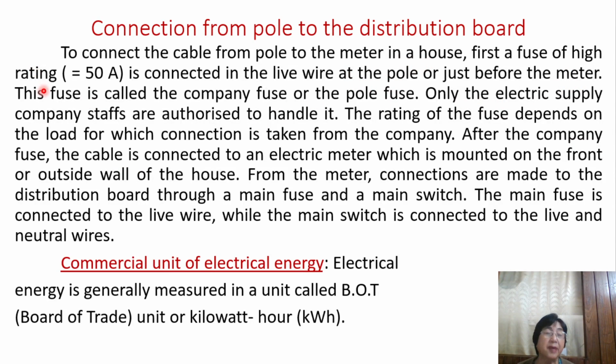Okay, this fuse is called the company fuse or the pole fuse. Now, who will handle this fuse? Only the electric supply company staff are authorized to handle it. Not you, not me, alright? Only the staff from the company that supplies electricity to us will handle this company fuse. Okay? The rating of the fuse depends on the load for which connection is taken from the company.